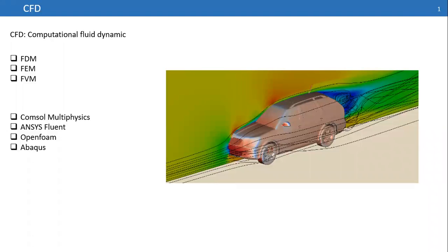When you solve your equations using finite difference, you separate them like dT over dt equal to T(i+1) minus T(i) over delta t. That's finite difference. But in finite element, you use integrals on different sides of your partial differential equation, and you solve those integrals on a specific volume that we call an element.